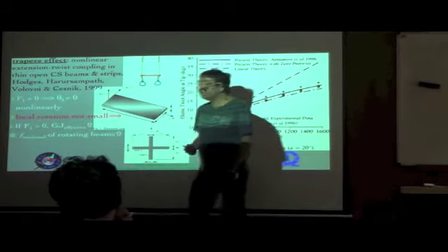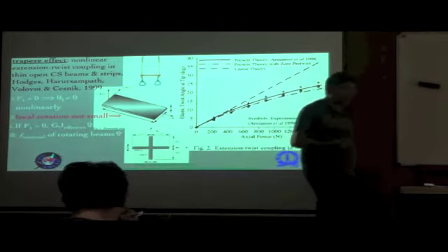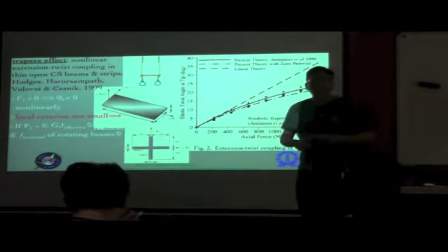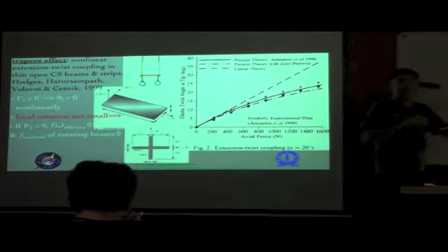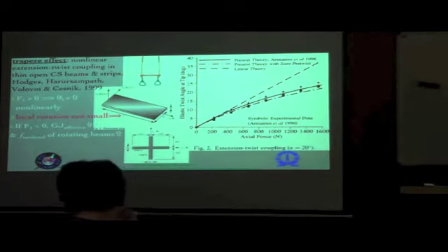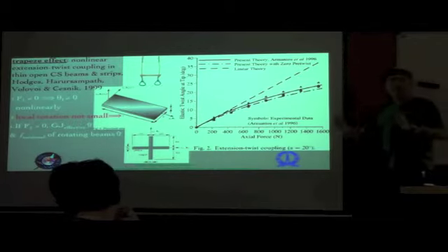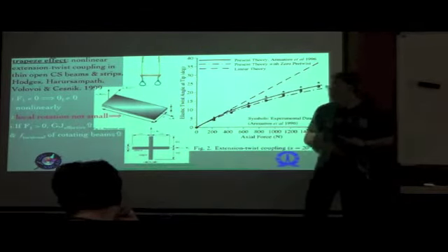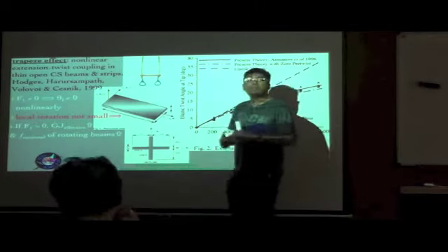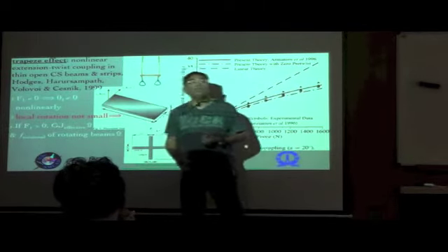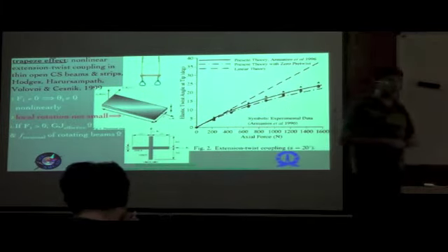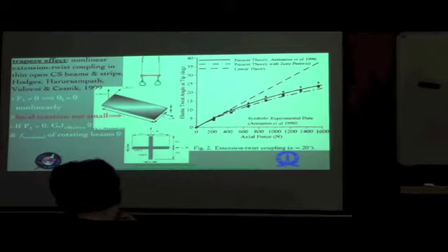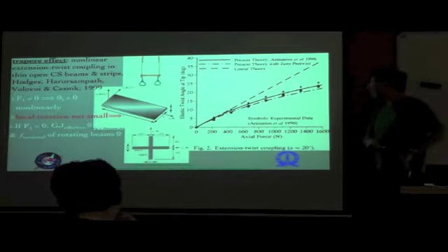torsion, will also increase. If it's a rotating beam, there is an axial load, whereas in the non-rotating beam there is no axial load because there is no centrifugal force there, unless you are actually applying a physical force which is axial. So a primary difference between the same beam in one situation rotating and in the other situation not rotating is that the natural frequency in torsion is basically larger for the rotating beam as compared to the non-rotating beam, and the reason is this.